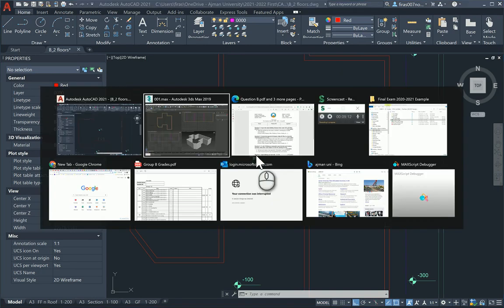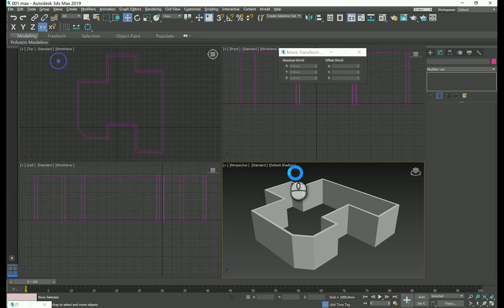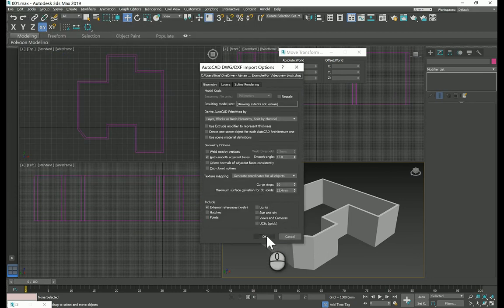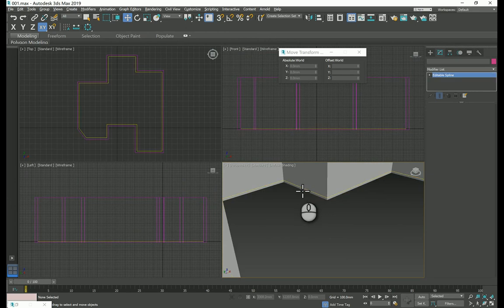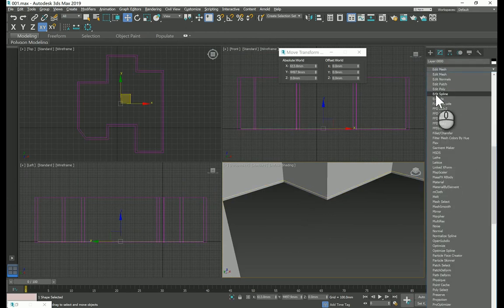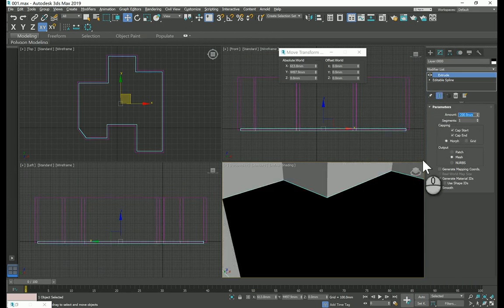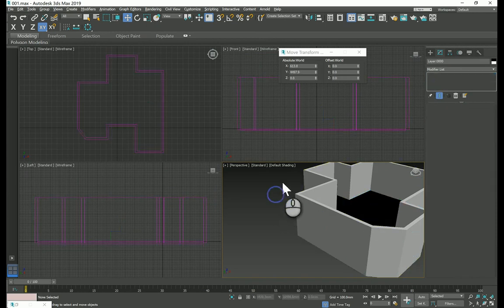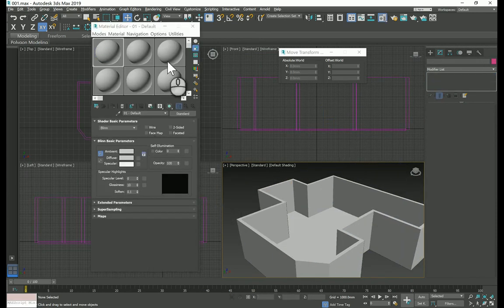So again, import, and the default thing for 3D Studio Max is everything to be set on 0. So I'm not gonna change the location of it. It's the default thing here. I'm just gonna add extrude for it, and it's a horizontal surface, so it definitely follows rule number 2, which is all the horizontal surfaces, if they are not being specified, should be -200. So that's what I'm doing right now, as you can see.